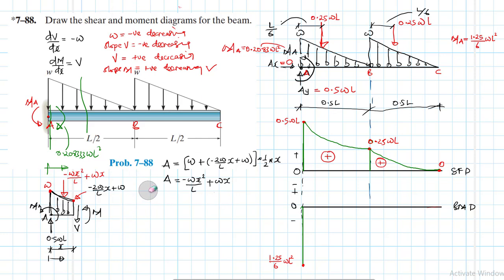There's no need for us to find the location of the equivalent force, because we are not calculating moment. We just want the equation for shear, which we are later on going to integrate so that we find the moment at B. This is one of the methods, not the only method. Great.